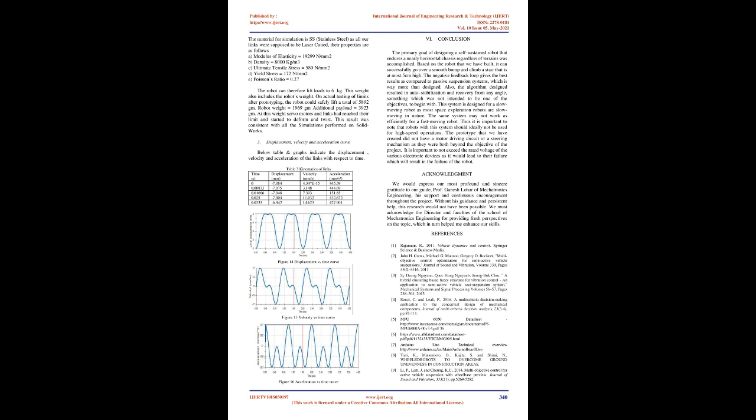Static structural analysis using SolidWorks was performed on the link to see how much deflection and how much stress is developed on the application of different amounts of forces, to find out the payload carrying capacity of the link. The material for simulation is SS, stainless steel. As all our links were supposed to be laser cut, their properties are as follows.